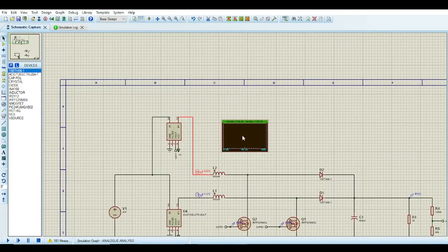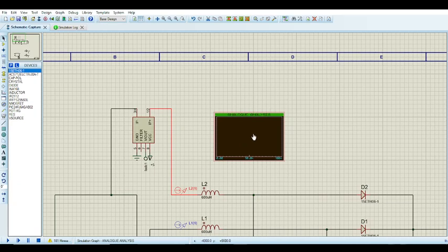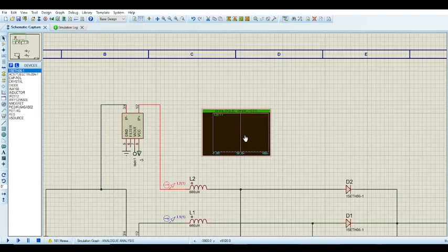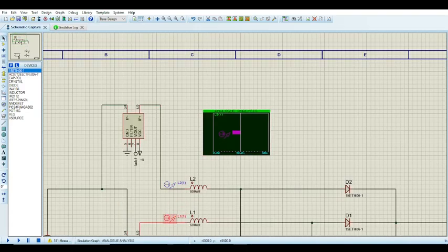Only the actual chip has some variations in terms of the VREF, obviously. So the VREF won't be 5.0 bang on. It'll probably be 4.95, 4.98, 4.97 thereabouts. But in terms of the processes, the function of the microcontroller, it's very similar to when you simulate it, in terms of what it does with the coefficients, etc. So that's why you should use it. Usually more trust in the microcontroller simulations and control than with just the regular spice analysis. But it's a start. Obviously, the best is just to chug it in and try it out and see what you get in the real world. But you gotta start from somewhere.